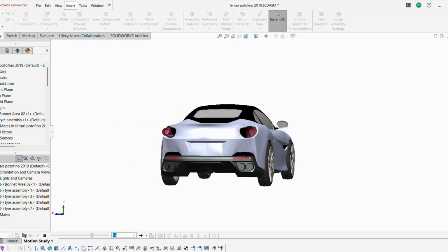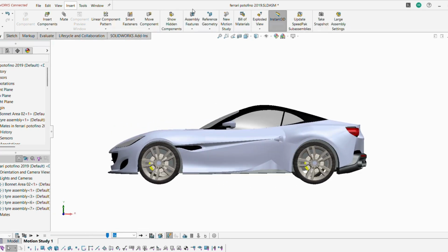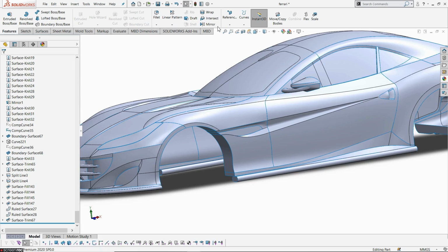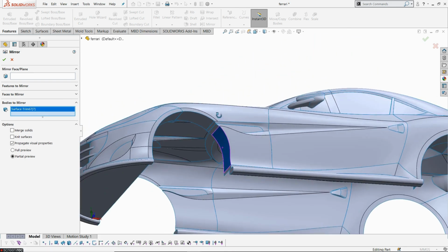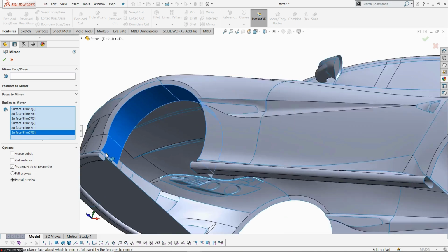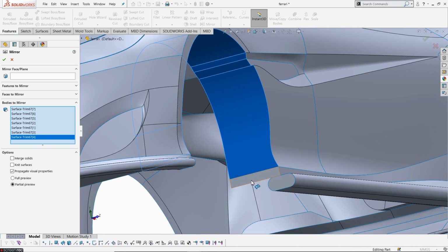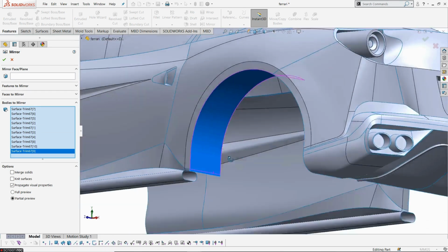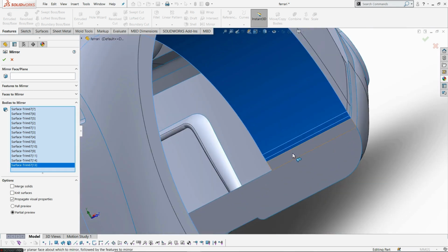Next one is automotive surface styling. This is a car design, a Ferrari car design. But this car has a lot of shapes in it. It is not easy to model all kinds of profiles in surface, because surface modeling is also similar to complex tools, because we cannot use one tool like a lofted surface and a boundary surface at one similar position. We cannot define a ruled surface or trim surface at one particular location. So we need to know the use of each and every tool by modeling all kinds of surface portions under this automotive surface styling only.